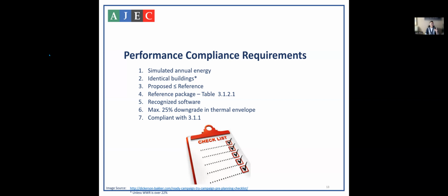Okay, so Toronto is zone 1. Toronto is in zone 1, and the heating degree days is around 3,600, 35 something. So around 3,600, that's the Toronto heating degree days. And the link I sent last time when we did the session, you can go to the link and type in the address, and it will tell you what the heating degree day is. That's where you can find the heating degree day for your project.